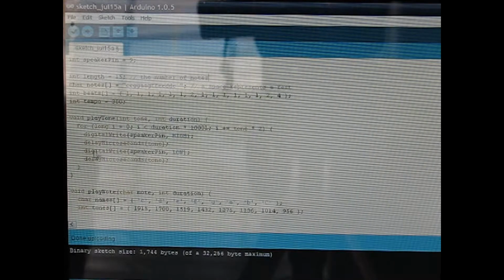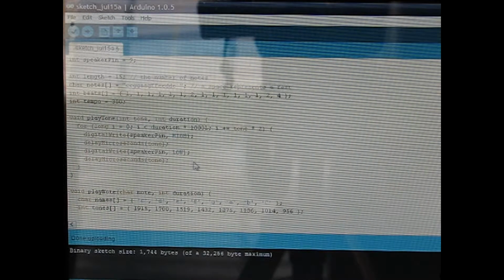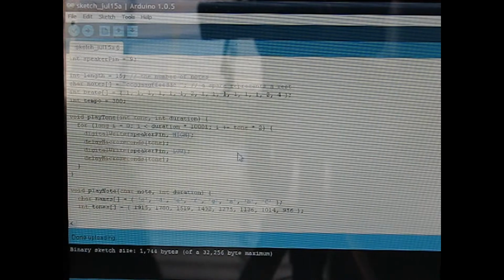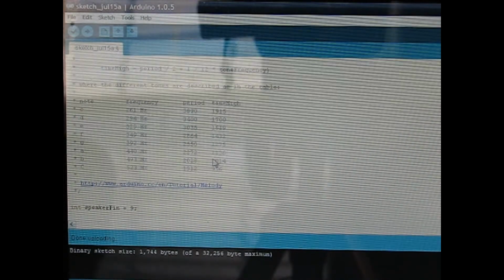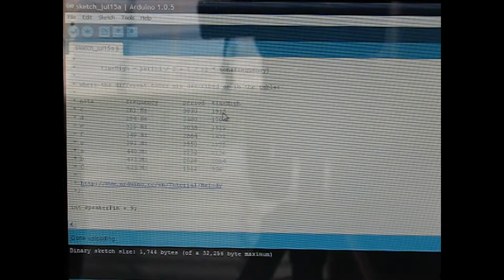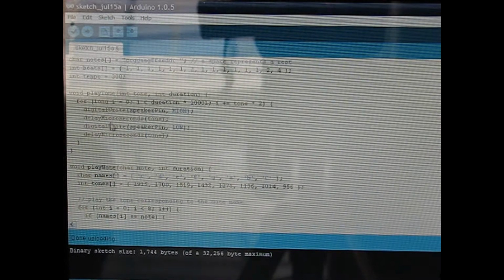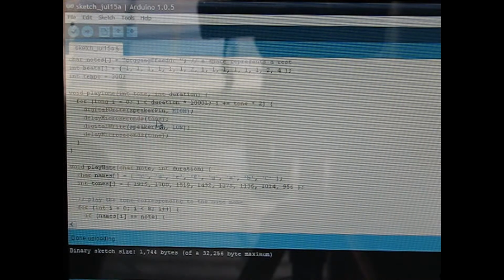So as the frequencies get higher, it increases the amount of square wave cycles, so you get the same length of note from this low B here to low C. They will be the same tone length, or tone duration, I guess, even though this will have more positive negative square wave, +5 at -5 volts cycles, but they'll be the same time length. And this high, and then delays to play that, and then low to play that.